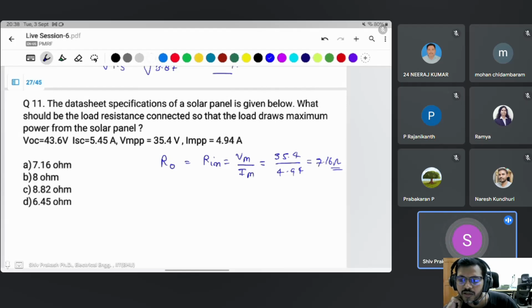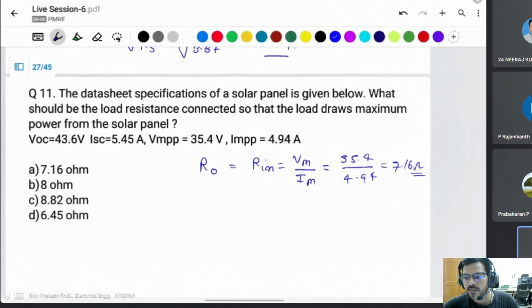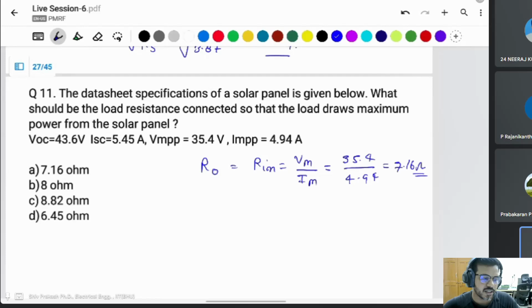No, no. You can operate in both conditions. It depends on the inductor current. If the inductor current is discontinuous, then it will be discontinuous conduction. If the inductor current is continuous, then you can say this converter is in continuous conduction mode.